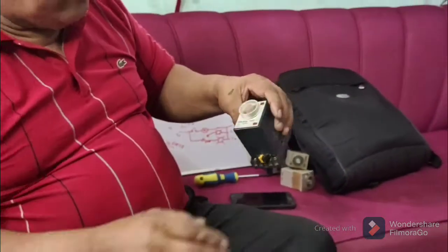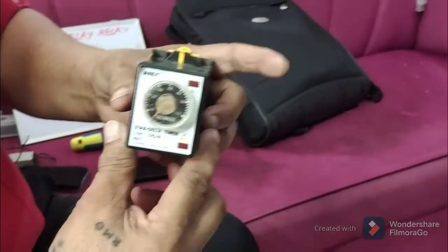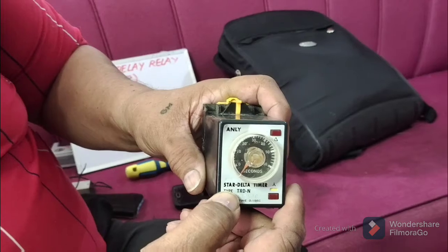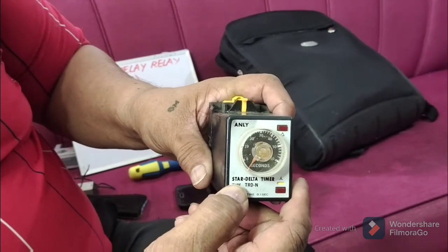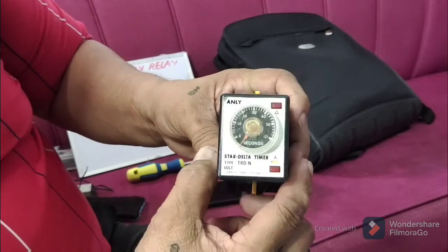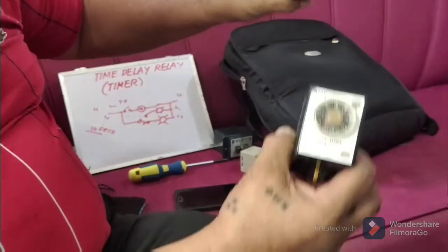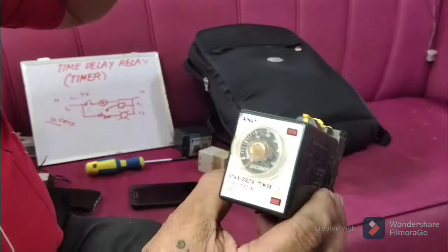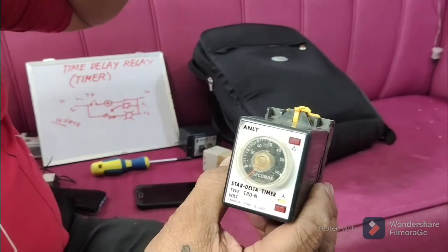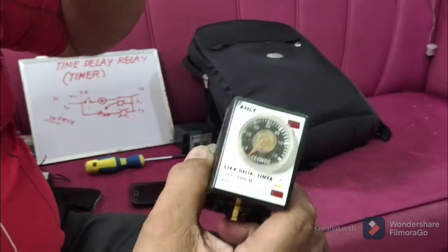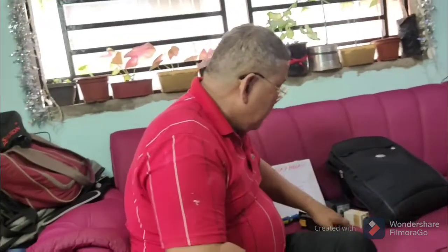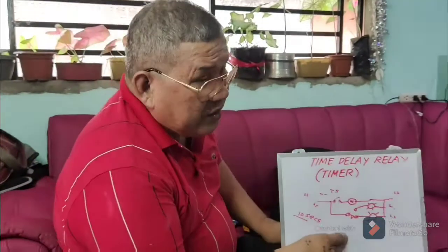Okay? So this one is still an on-delay timer, but specifically used in star delta. We will come to that star delta connection. That is part of the reduced voltage magnetic starter. So technicians are not actually using this one. They are using the Y delta or star delta timer. But this is an on-delay timer. Okay? So that is the one.